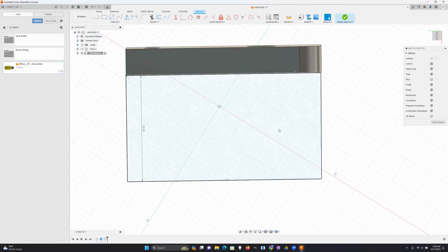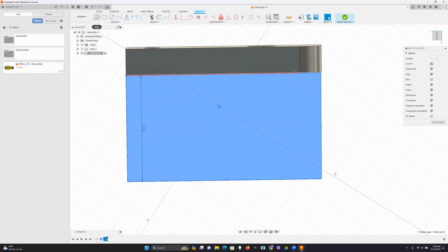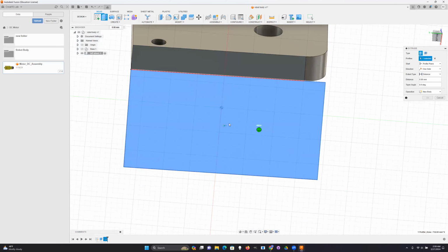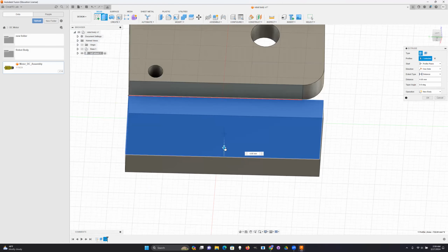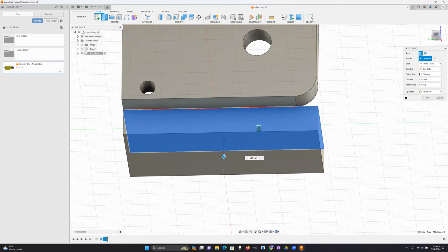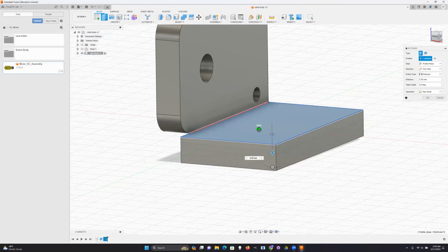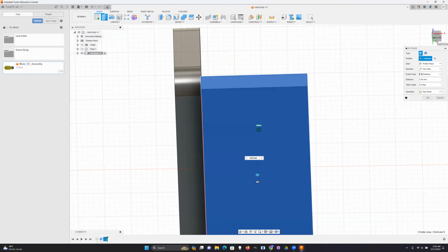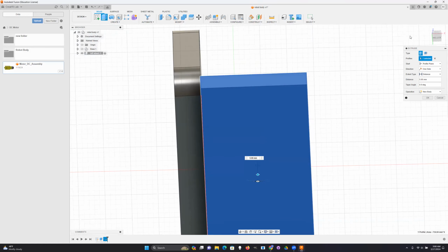So if I'm pretty happy with this, the same thing I want to do is hit the extrude, click on the face, then you go to solid, extrude, and then you want to go this way. You see the little arrow, then you can extrude down. You could do 5 millimeters if you want. You could rotate to make sure that you like it. Right now, because I did the line here, it's not really gonna join to this, but that was my mistake. I should have actually started the line over in this area a little more.